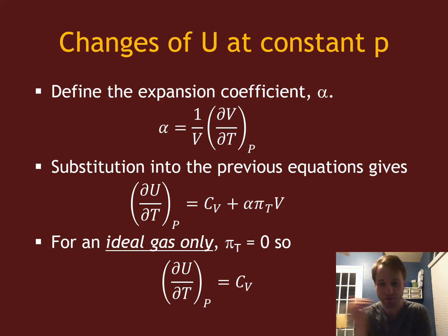So if you have something that fits nice and smooth into some other spot, but then you're using some material that has a large enough expansion coefficient that at the temperatures you're working with, that volume is going to change by some significant amount, to where now it no longer fits, then your machine is going to break down. So this is something that is often known for a lot of materials and measured, depending on their applications.